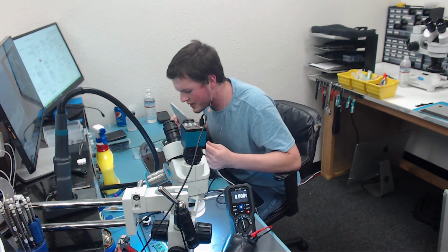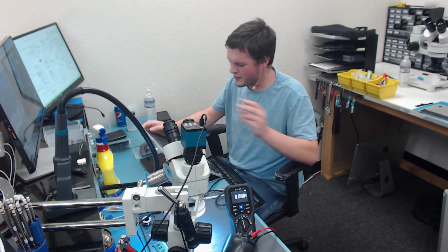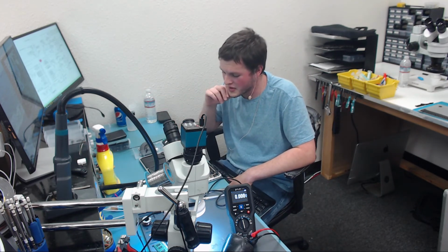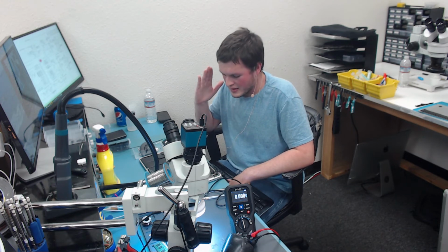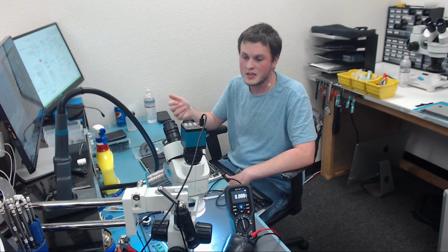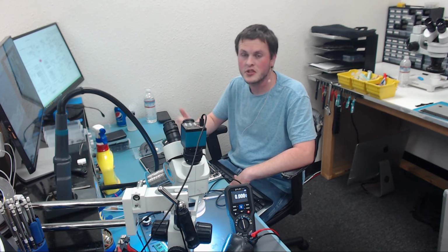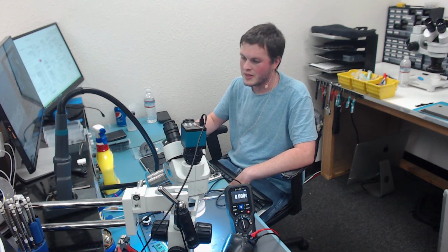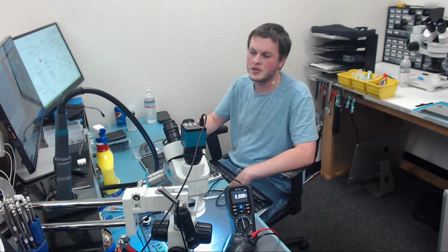So, this is a typical U8900 issue. The VRAM issue, I don't think that had anything to do with it, but it did have coffee on the VRAM chip. It's probably not going to like that. Over time, it's going to corrode. So, let's go over this again. I've done this so many times I can't even count. I've done videos on this, however, I still get people that think it's a GPU. I get people all the time asking, do you fix NVIDIA graphics card issue? I was told it's the video card, and I tell them, no, it's not the video card.